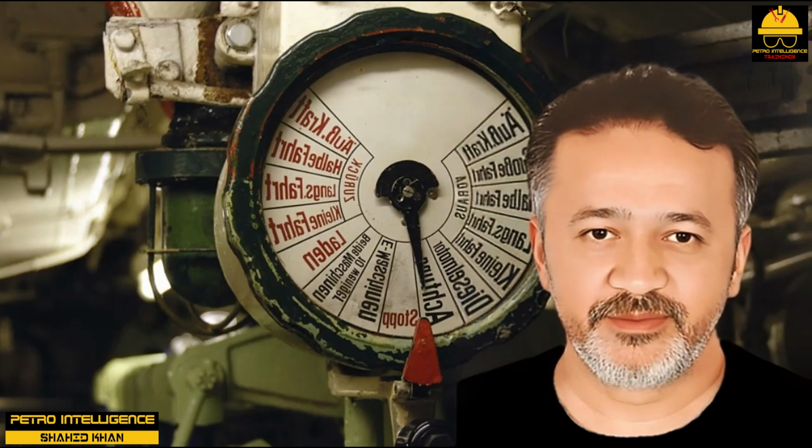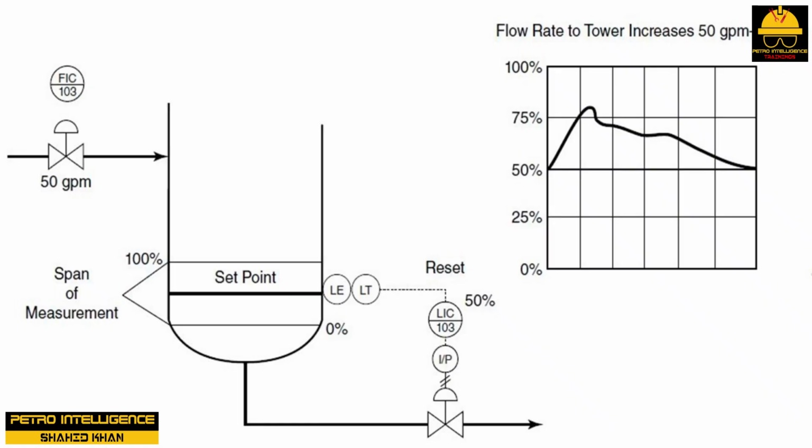Proportional band. The proportional band on a controller describes the scaling factor used to take a controller from 0% to 100% output. If the proportional band is set at 50% and the amount of lift the final control element, a globe valve, has off the seat is 4 inches, the control valve will open 2 inches.